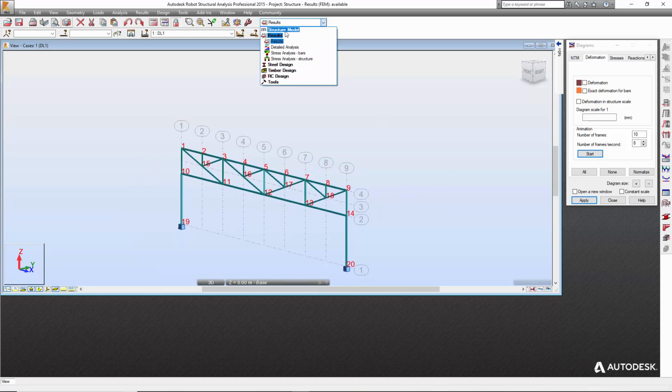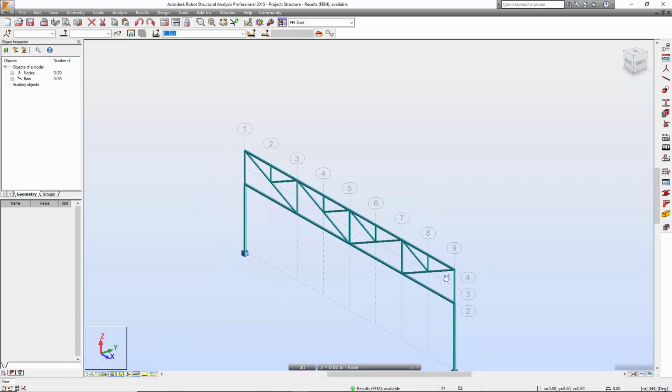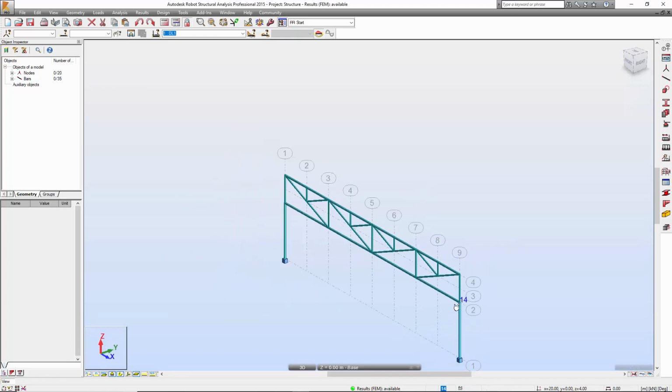Let's come back to the structure mode and start. I don't need this node, so let me disable it, and then I draw this and rotate this one a little bit in here. Say, for example, the clients need a 6-meter opening space between here, so this column needs to be removed and replaced by a beam from this end 3 meters away, connecting to another one 3 meters away from here. So connecting this one, supporting this truss.